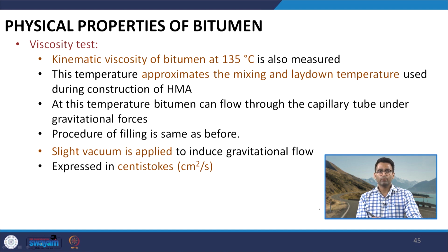If you remember, when we talk about bitumen, we have to see how the bitumen undergoes various temperature ranges from production to in-service life. During the production period, bitumen is exposed to very high temperature. At this particular period, at the mixing plant, we have to ensure that the bitumen is fluid enough so that it can be pumped and mixed with the aggregate particles.